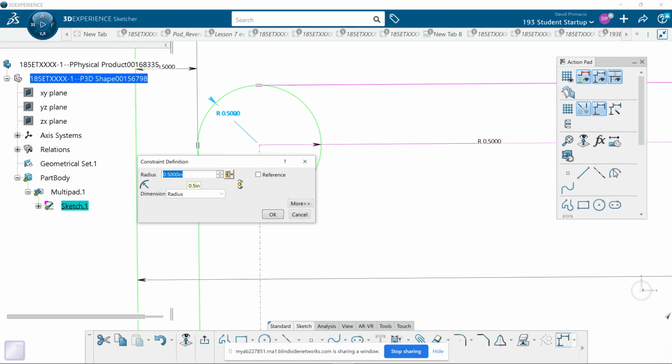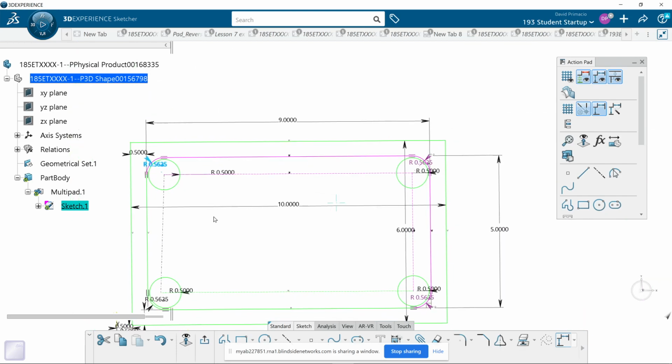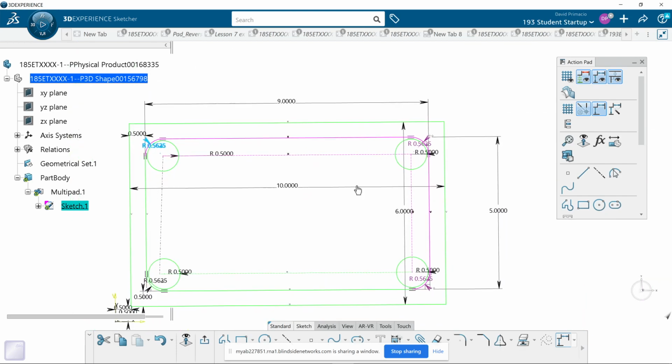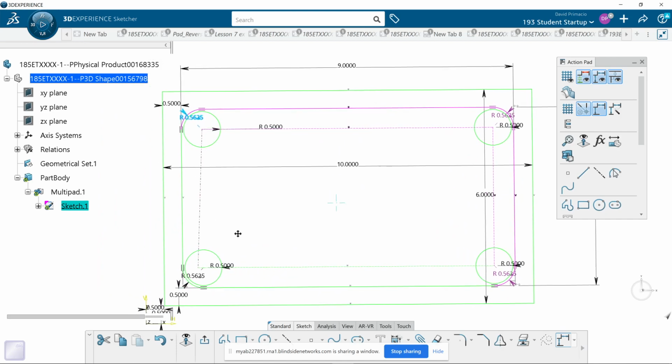Now, what I would recommend to the engineering is take that dimension and go to the next fraction that's the most common. Does anybody know what the most common fraction would be next? 9/16, and that's 0.5625 is 9/16, right? Yeah. So if you change that to a 9/16 radius, and I wish it would have, oh, it did, it changed all of them to 9/16. That would change this radius.